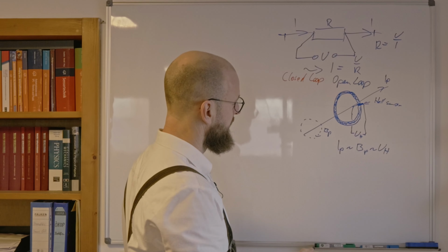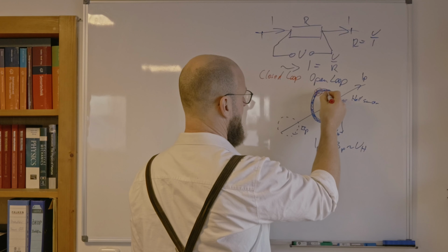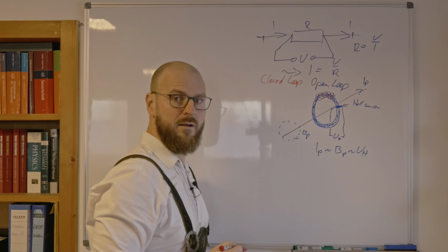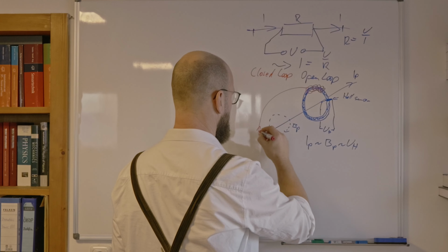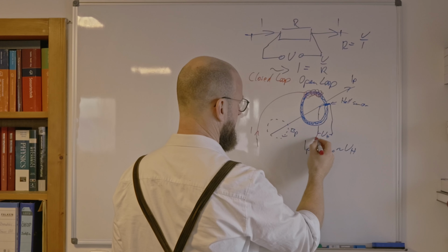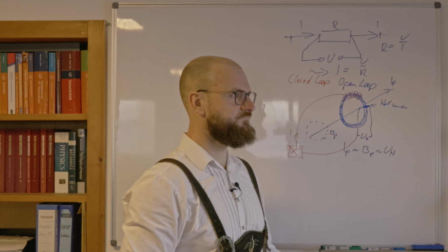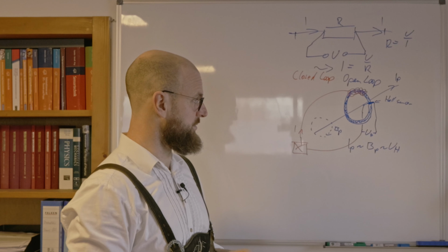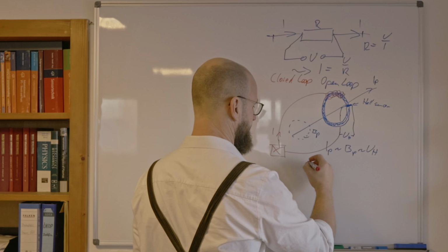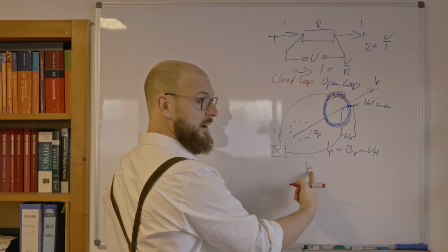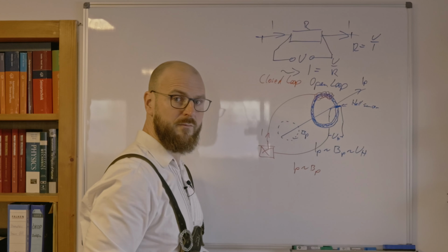The principle is still the same, only the way we deal with the magnetic field will change. Meaning, we add some coil around that iron ring we have. And that coil, the current which is driven through here, is directly controlled by the Hall voltage we measure. Meaning, we start the measurement by having some primary current we want to measure, which exerts a directly proportional magnetic field.